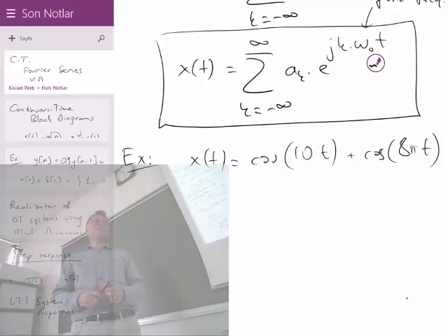This is not a periodic signal, because there is no fundamental period. The fundamental frequency is 0, the fundamental period is infinity. This is not periodic. You cannot find omega 0. And since you cannot find omega 0, you shouldn't talk about the Fourier series coefficients and all those things. You should quit answering immediately, saying that this is not periodic. That would be the correct answer.